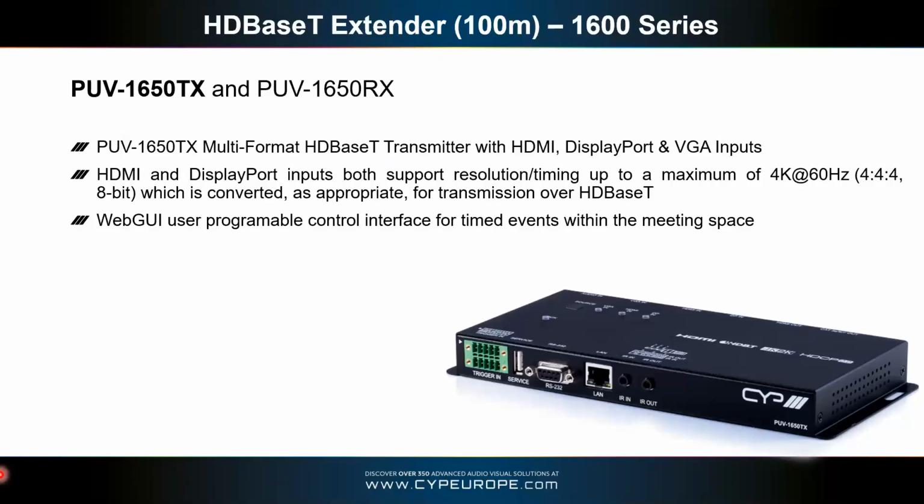It has macros, which are multiple commands, multiple things that go off at the same time. So you can add different commands that do different things, both to the unit and to third-party equipment that are connected either IR, RS-232, or Telnet, so you can control them as well. And then you can stack these commands into a macro. So if you wanted a macro that was basically powering the room on, you could do that type of thing.